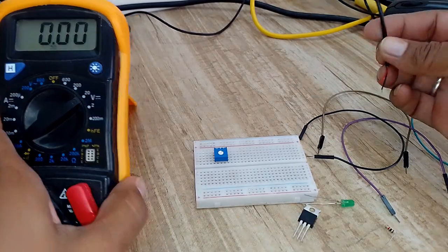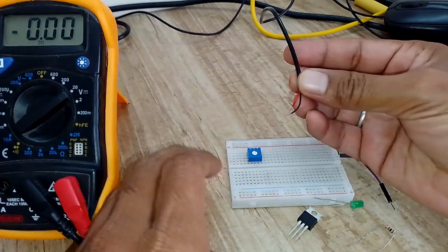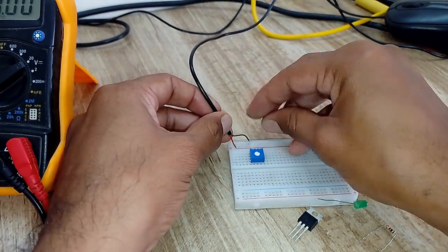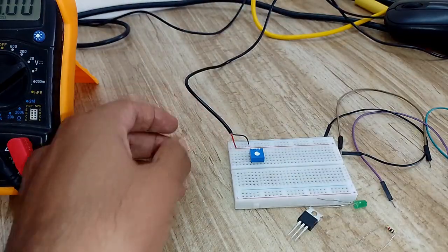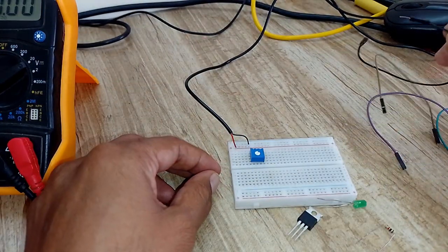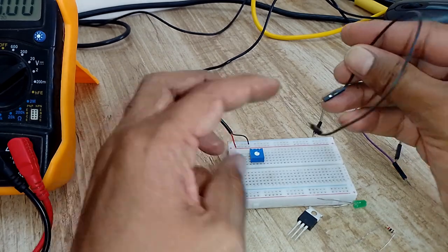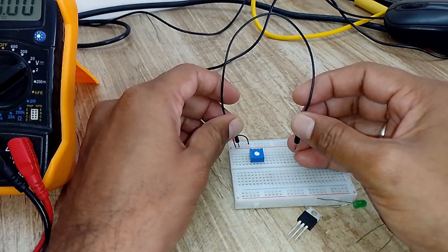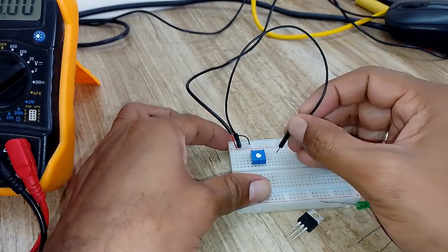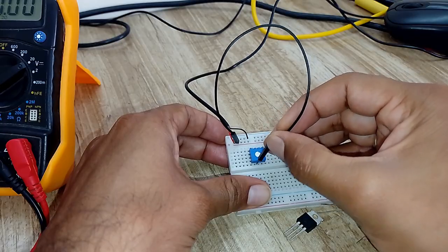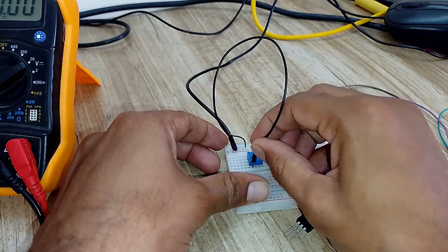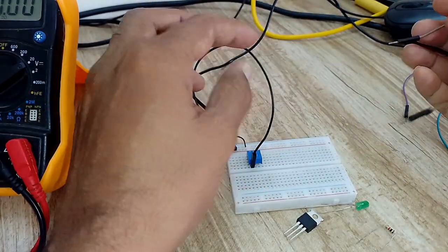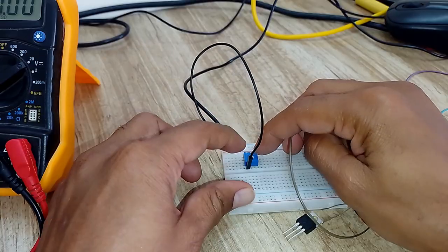So first we will connect our adapter, which is 8 volt and 0.5 amps. So connect your adapter positive and negative. So this is your trim pot. Usually this trim pot will vary the resistance so that we can vary the supply. So from positive I am connecting it to one of the pins, that is the leftmost pin. From the center pin, see, when we vary the resistance, the output at the center pin varies.